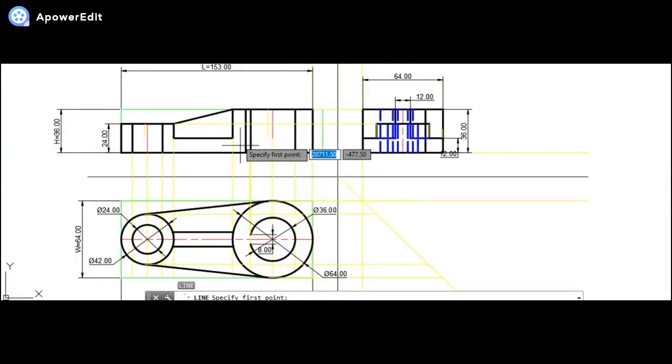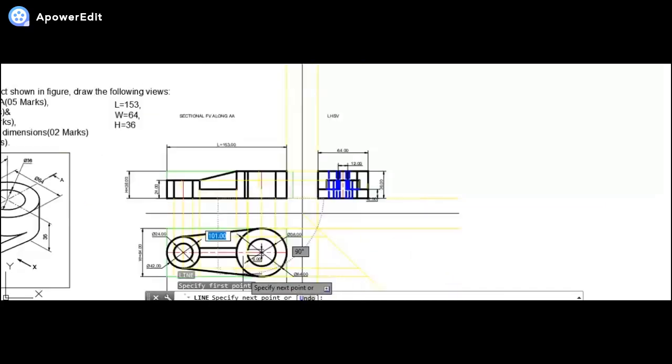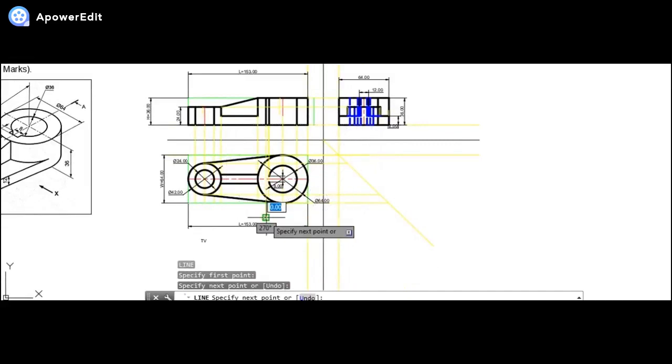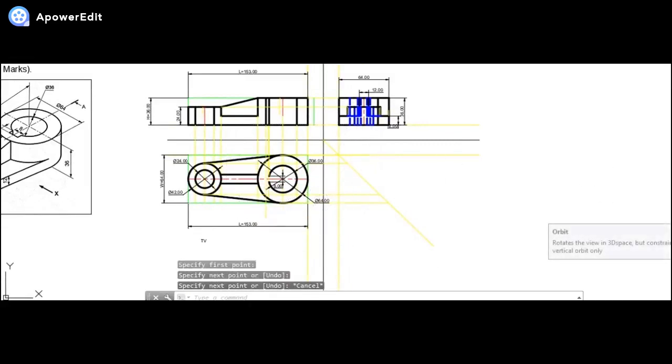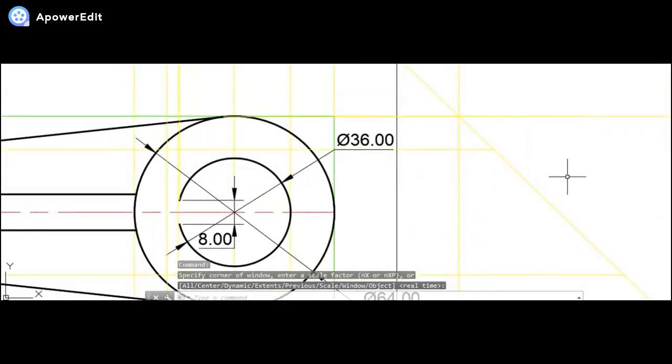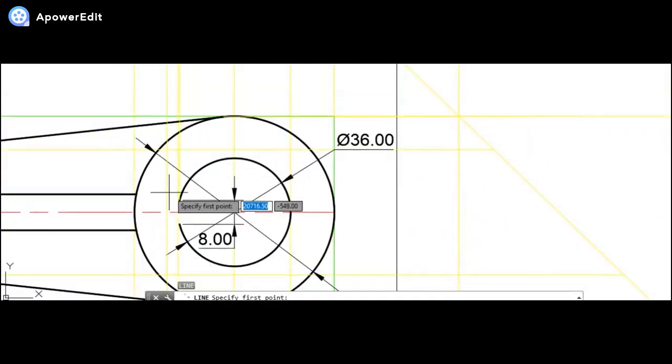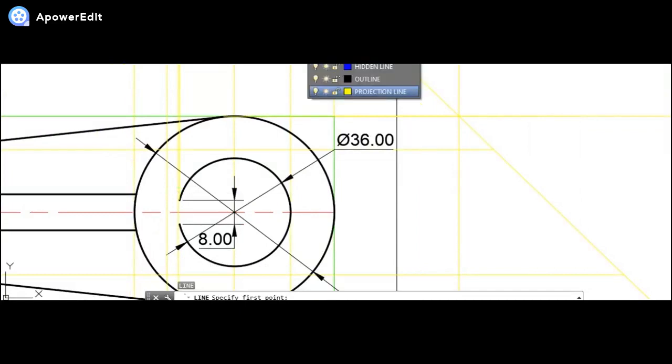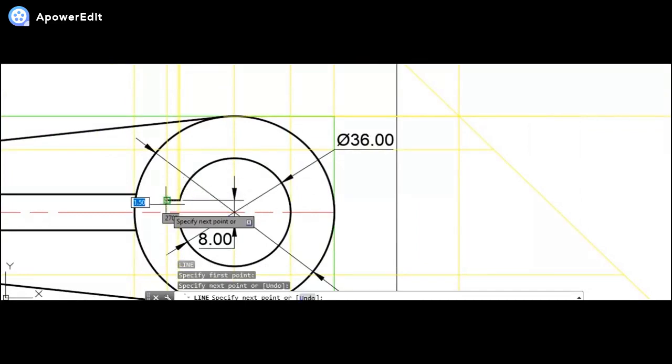Now what I want is, from here I will be drawing a straight line down, which will give me the exact dimension, like this. Only from here further lines will be drawn, so that exact 4 mm distance will be getting without any problem.